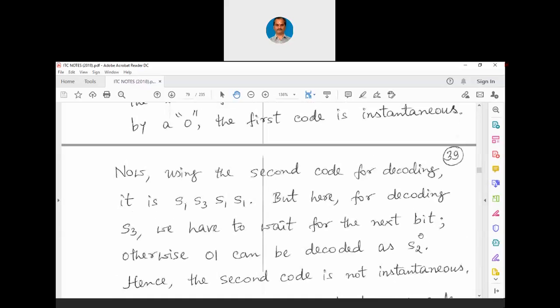That sequence goes into the modulator. In the modulator, there is a 2.4 GHz oscillator and there is a VCO. And using this 2.4 GHz radio carrier, the binary sequence is being transmitted through the antenna. Now that sequence goes all the way to your mobile phone or your laptop, through either a wired or wireless channel. In your receiver, you will have a demodulator after the antenna, where from the radio frequency of 2.4 GHz, it is demodulated and the binary sequence is obtained.